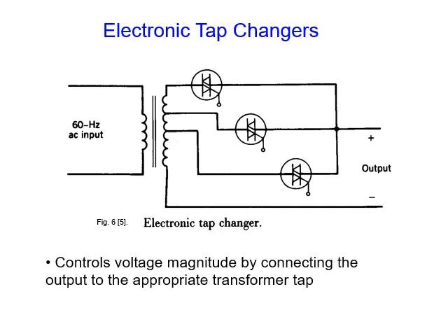Now, electronic tap changer. You know the transformer here, but we want the output to be a different voltage, or to control the output voltage, as you can see here. So we have taps. In the past, it was done manually. Today, we don't need this. We use a triac, okay? A triac is like connecting two anti-parallel thyristors. You remember the AC voltage controller? Yeah. A triac gives the same effect. It's one piece, but it gives the same effect here.